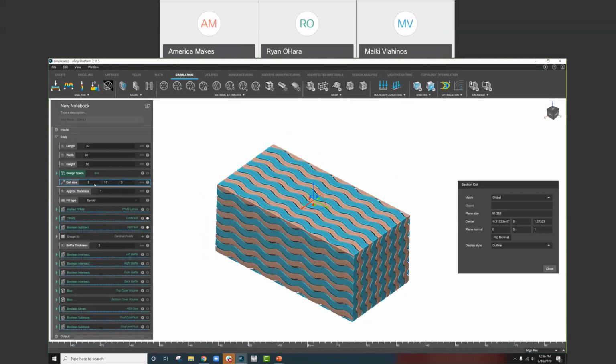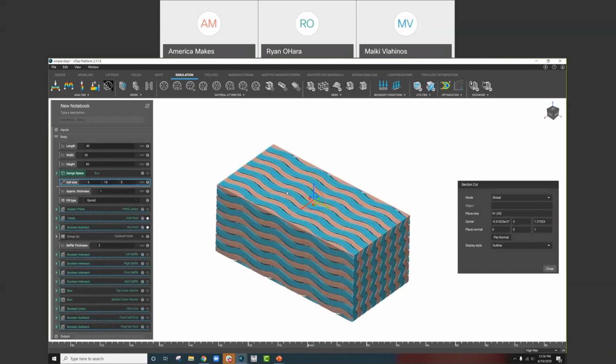We're holding the cell size constant in the direction that is normal to flow, in the X and Z axes. And in the Y axis, we want to stretch that aspect ratio. We're in the works of doing a study on that, looking at how effective changing that aspect ratio and stretching that shape out might be. You can get a little bit of a glimpse of that; we're doing a talk next week, and we're going to touch on this a little bit as far as pressure drop goes.